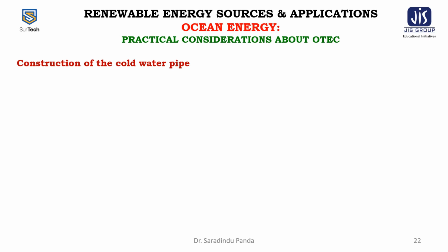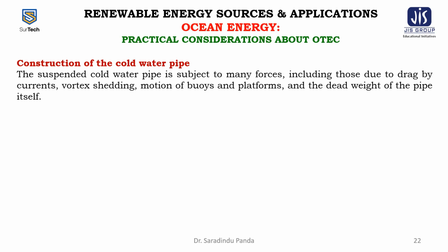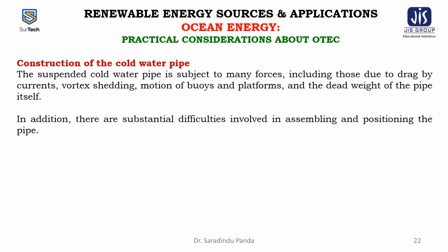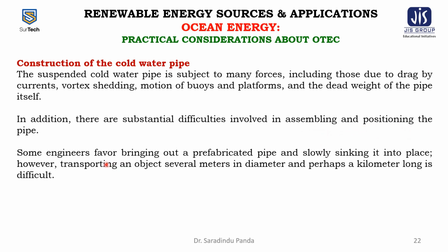Construction of the cold water pipe. The suspended cold water pipe is subject to many forces, including those due to drag by the currents, vortex shedding, motion of the waves and the platform, and the dead weight of the pipe itself. In addition, there are substantial difficulties involved in assembling and positioning the pipe.